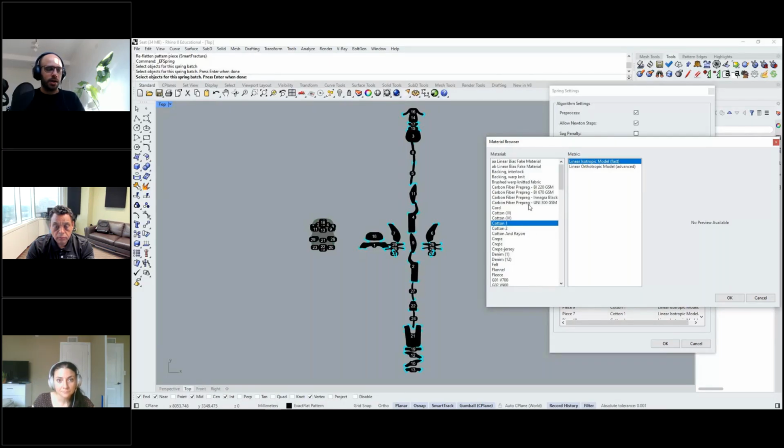So the material that we choose here is going to affect the shape of the flat patterns. If the material that you're looking for is not within this list, we do have an agreement with a lab in the US where you can send a sample of this material and it can be tested. Within 5 to 7 business days, you'll be able to add your own specific materials to your material library if needed. That has a cost of around $50 per material sample, so it's really cheap. And that way, you'll be able to simply add your own materials. Nevertheless, I would say that most of our customers get away with using the materials that we already have in the list. I'm going to go for laminate material for car seats in this case.